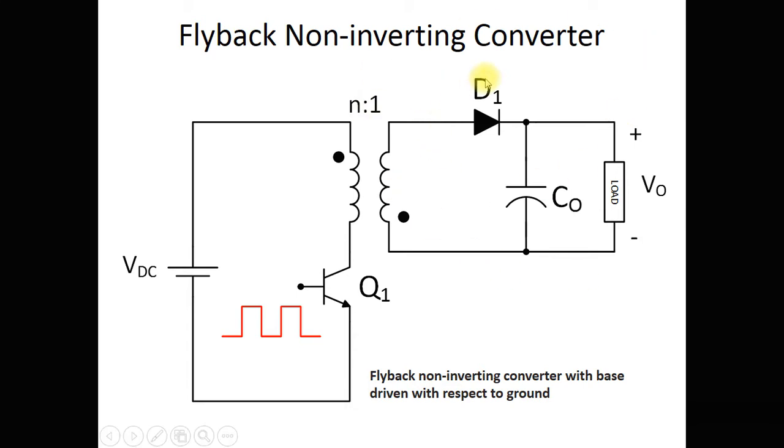buck converter. So this part, if you look carefully, looks very much like a buck converter. In fact, it is very simple to visualize this, because this capacitor will be acting only as a filter capacitor. So whatever ripples are over here will be dampened or bypassed. The AC content will be bypassed by this capacitor.